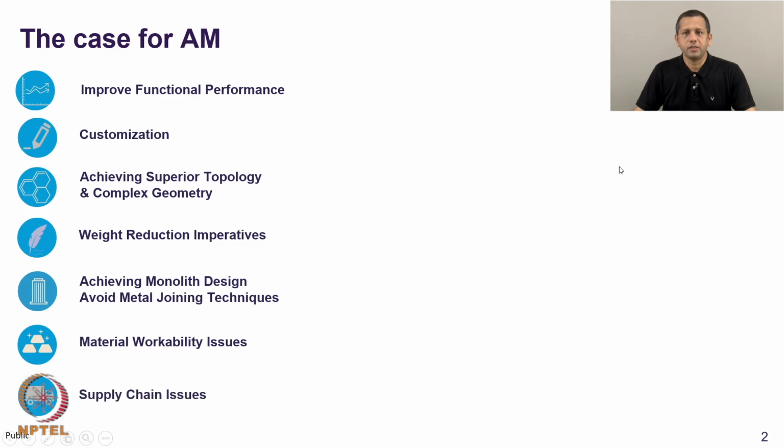Additive manufacturing offers as-needed manufacturing of really complex geometries and components. Thus, it also solves a very large issue in manufacturing, which is called the supply chain issue. We can make parts as needed. We do not need to have a large inventory of raw materials and of the finally made parts. We do not need to create individual components of a very large machine as mentioned earlier. Thus, just a monolith structure can be created and can be used immediately.